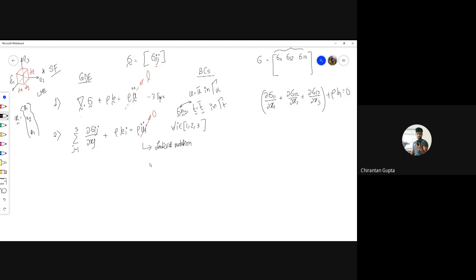No, sir. The last line was not clear. That sigma n equals t in the traction boundary condition. Sigma n equals t, that is the very definition of traction. Or rather, you can call it the very definition. The thing is, we actually got the expression of sigma through this kind of an exercise, and then we define the matrix that relates the traction to the normal as the Cauchy stress tensor. So the very definition of the Cauchy stress tensor is this equation, Cauchy's equation. And that traction happens to be known in gamma t.